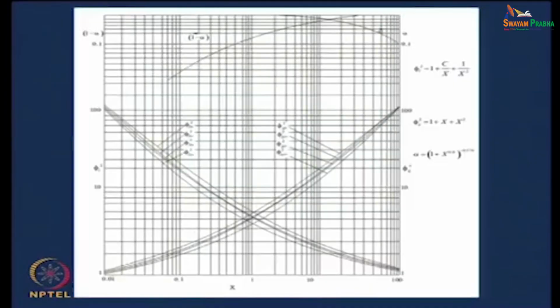But very frequently what people do, they find out the frictional pressure gradient from here, and accordingly they calculate the gravitational and acceleration components and they can calculate the total pressure gradient. That is also done for this particular case, and we find that the correlation which I have shown you graphically here, in essence, balances the frictional shear stress versus the pressure drop. Okay.